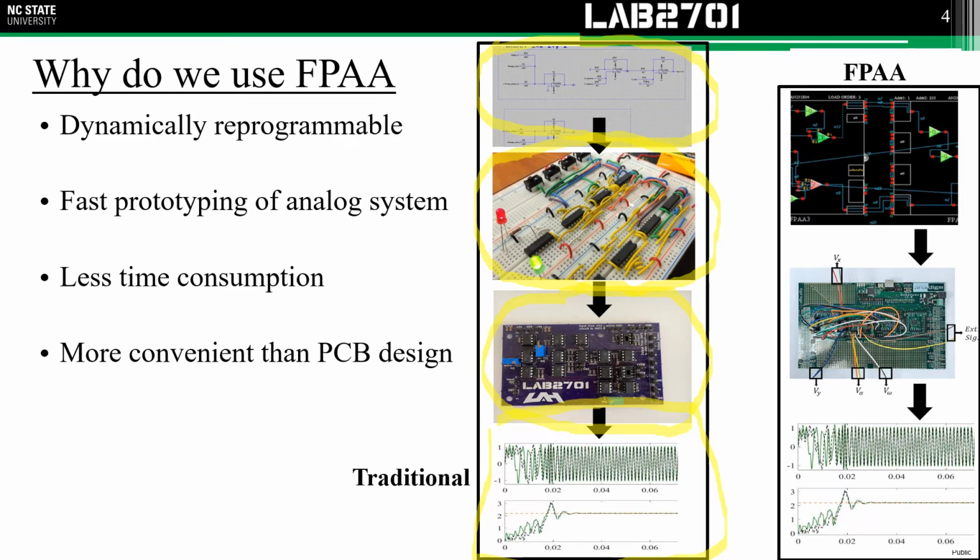So when people are thinking about a new design, we can actually use a simulator. The FPAA that I use is from the Anadigm company. They have a simulator here, as you can see. In this simulator, you can put a lot of different modules. Each module can act as, let's say, an integrator or an inverting or non-inverting amplifier.